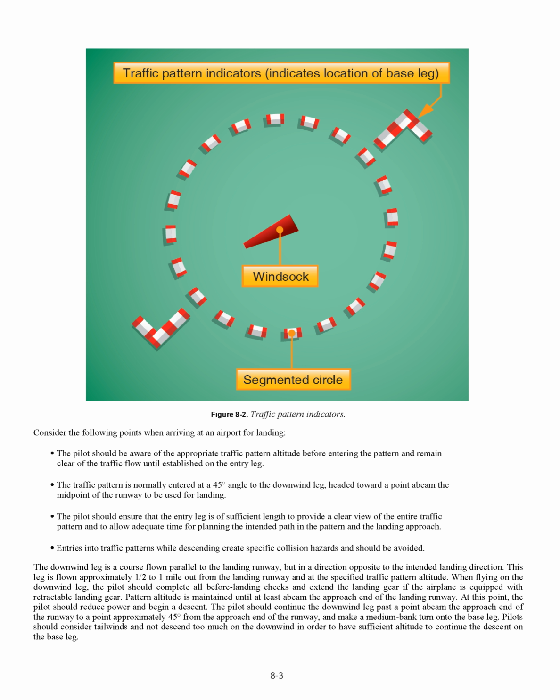The pilot should ensure that the entry leg is of sufficient length to provide a clear view of the entire traffic pattern and to allow adequate time for planning the intended path in the pattern and the landing approach. Entries into traffic patterns while descending create specific collision hazards and should be avoided.